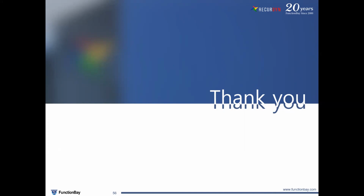Yeah, so as far as updates on the belt modeling toolkit, as James mentioned, we have that display of the contact forces. There are not any changes with respect to the basic definition of the belts. In the case of the belt modeling, you're going to define stiffness for all degrees of freedom. Basically, the belt is being looked at as a bunch of segments, and then there's a 6 degree of freedom bushing connecting the segments.